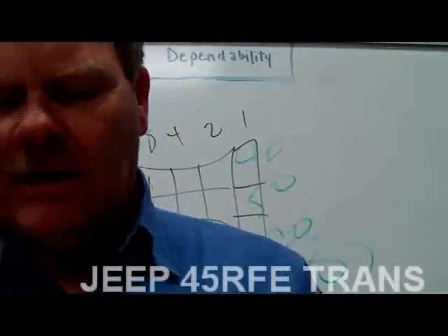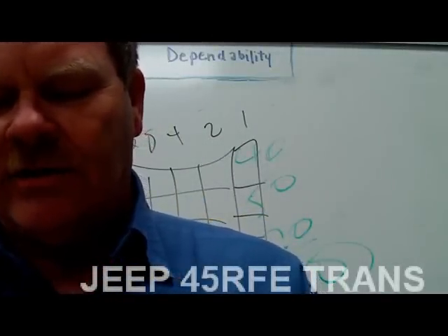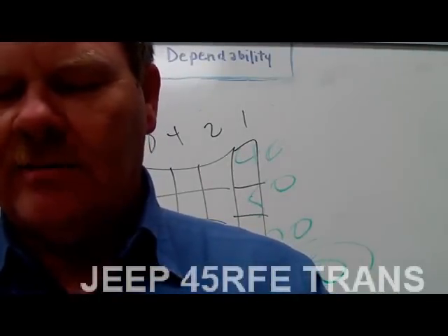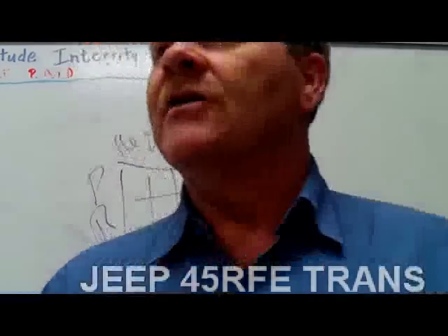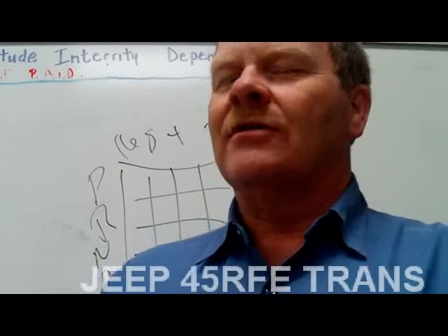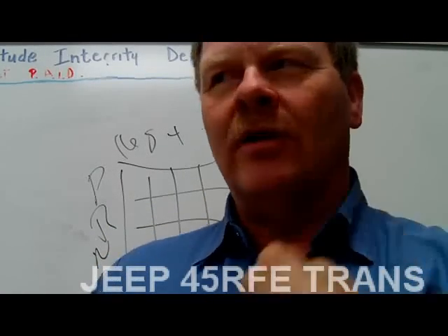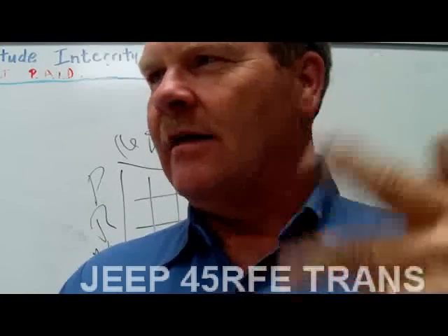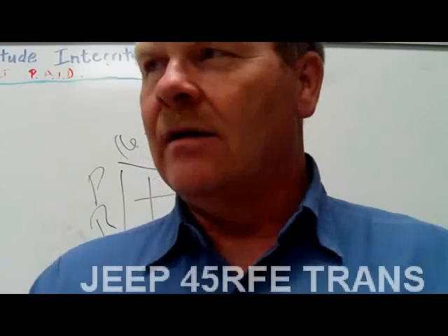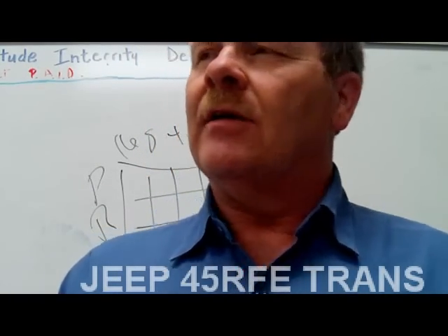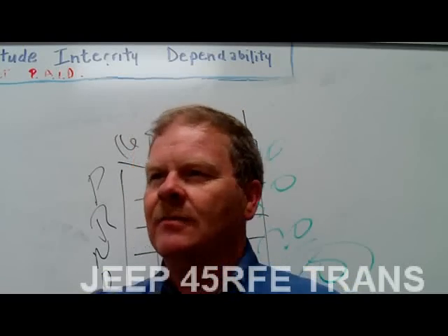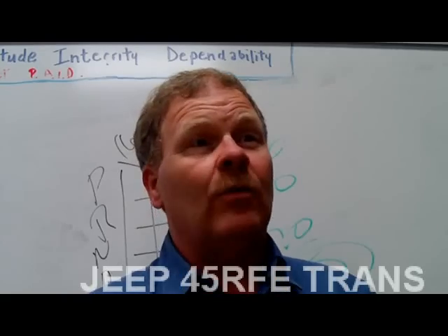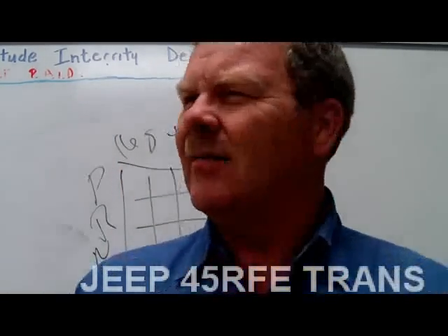All right. So it uses engine coolant temperature sensor reading, which it gets from the PCM over the PCI bus, to calculate transmission temperature if the transmission temperature sensor is out of range. So it says, if my transmission temperature sensor is dead, then I can use engine temperature to pretty much figure out what my transmission temperature is. Because the coolant and the radiator in most cases are all pretty much the same. Let me tell you this, when you plug a scan tool in, you compare a whole bunch of sensor readings: transmission temperature, intake air temperature, engine coolant temperature. If the engine's been sitting there for 4 or 5 hours, they ought to all be the same. If you got one that's out of range, something's wrong with that sensor. Got that? That ain't complicated, is it?